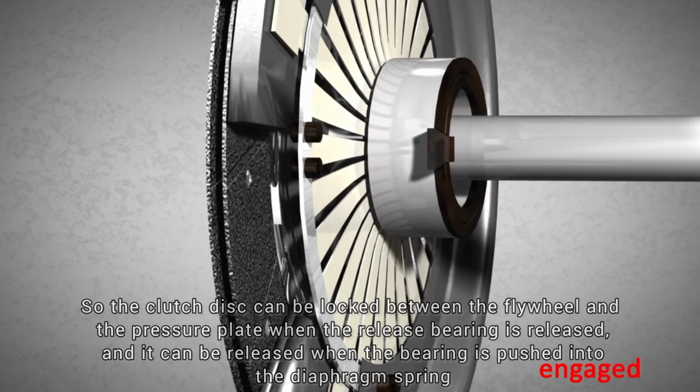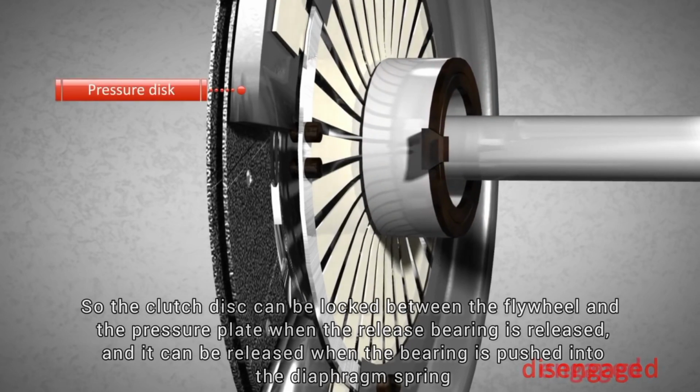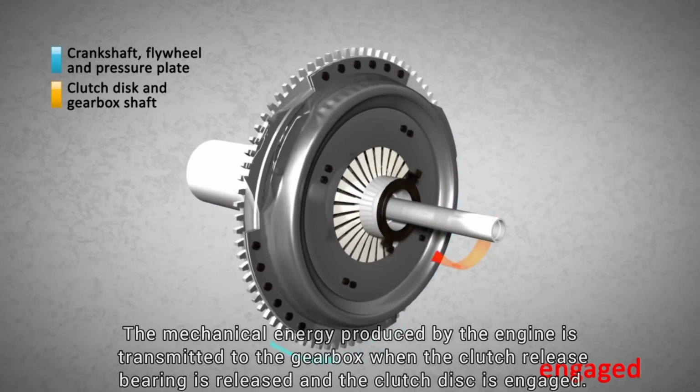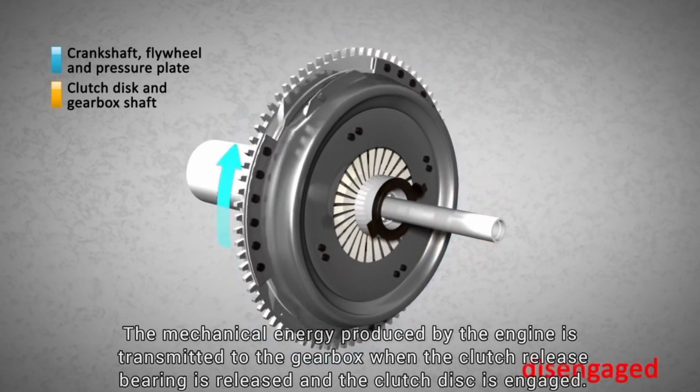So the clutch disc can be locked between the flywheel and the pressure plate when the release bearing is released, and it can be released when the bearing is pushed into the diaphragm spring. The mechanical energy produced by the engine is transmitted to the gearbox when the clutch release bearing is released and the clutch disc is engaged.